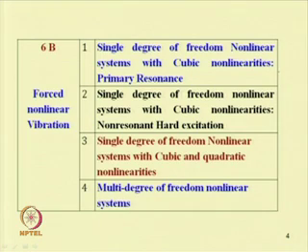Unlike in free vibration, where in the presence of damping the response decreases and finally may die out, in forced vibration of linear systems we have seen that when the forcing frequency equals the natural frequency, we have the resonance condition.